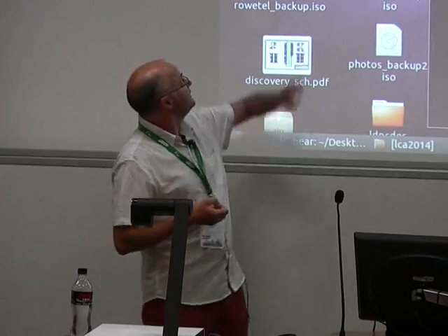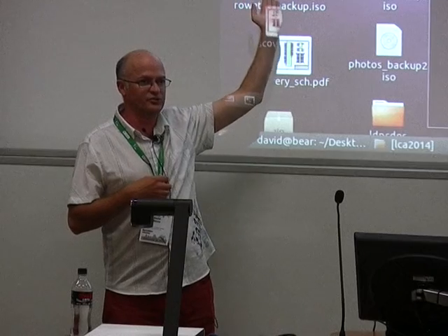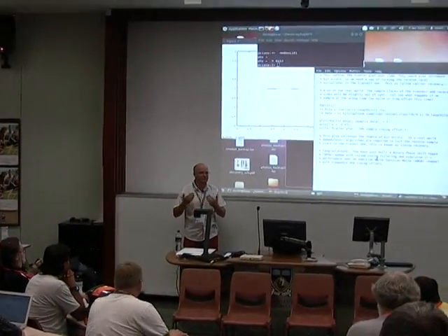Easy question, but just looking at the code there on the scatter plot, you're plotting the real and imaginary parts. What does the imaginary part represent? Someone's found that I'm plotting on the y-axis the imaginary part of the signal, and on the x-axis the real. The imaginary part is 90 degrees out of phase with the real, and it's a way of just conveying the phase of the signal through the maths. It's real and imaginary as in complex numbers.